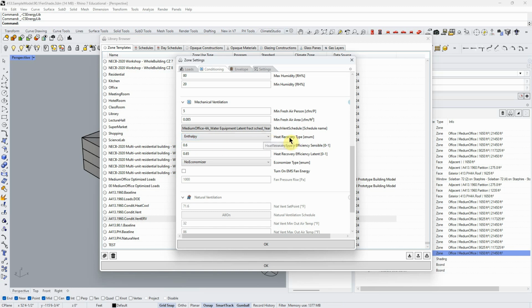So basically, all we're saying is that we're bringing in fresh air, and there's a technology that's pretty straightforward by which we can. We're exhausting stale indoor air and bringing in fresh air. The stale indoor air has the temperature that we want, and what we're bringing in probably doesn't. So there's a way of transferring heat energy, which is called sensible. That's what this setting would be. There's a technology called an HRV that does that.